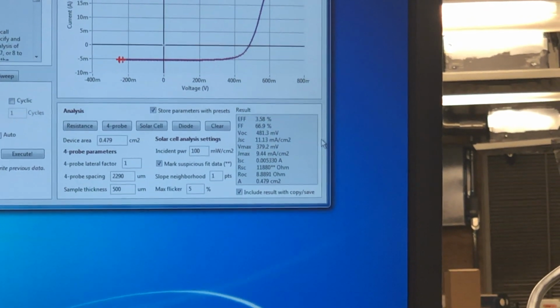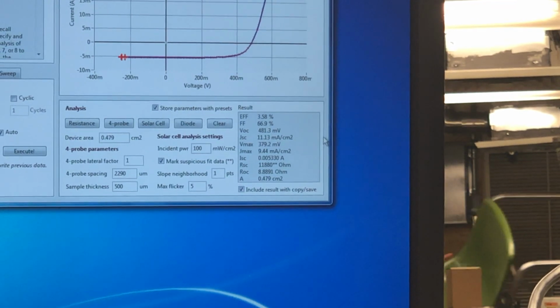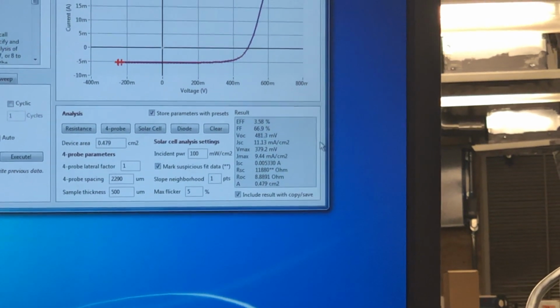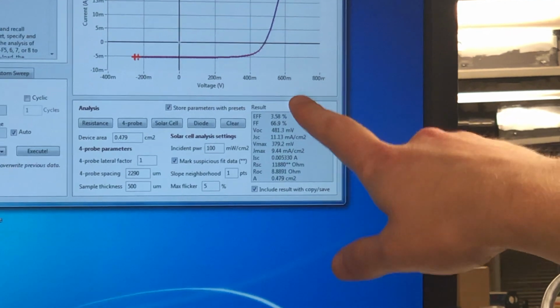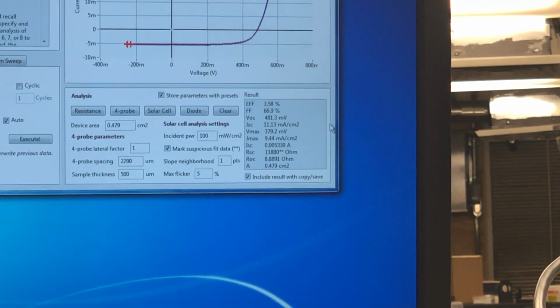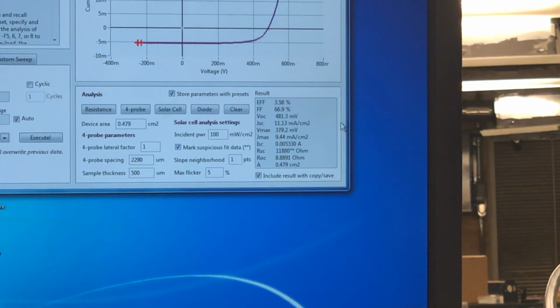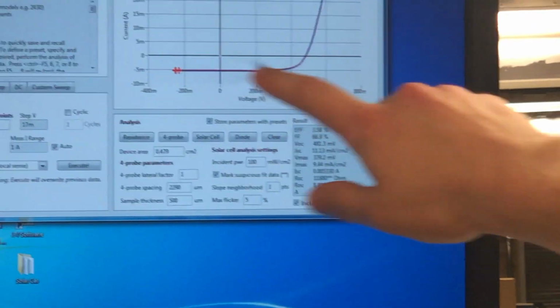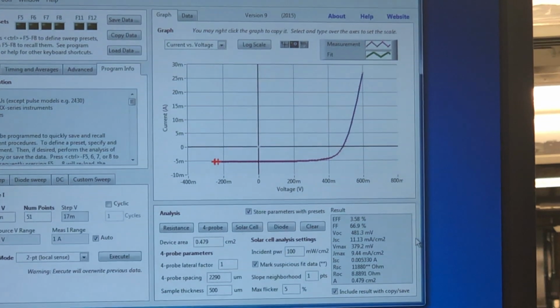One of the things we should do for the assignment is to calculate all these values manually by hand, and then try to see how close you get to the given values, just to see if you understand the theory. Be careful with negative values, again, where it's negative current in the raw data, but obviously your power is not going to be negative.